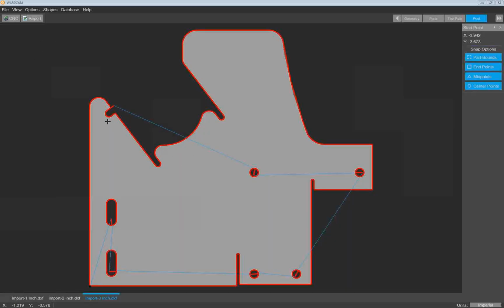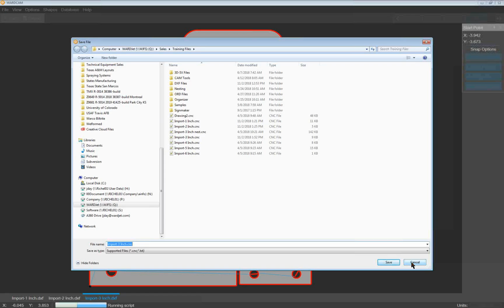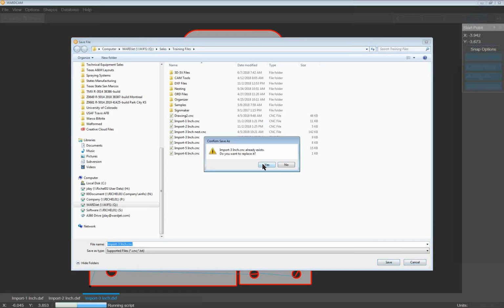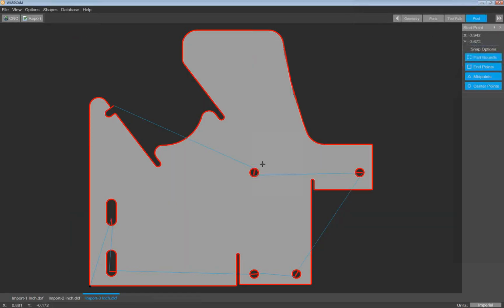Now, if you don't care about seeing the CNC file every time, or the report, if you go up to this options area on this last screen here, you've got these check boxes, and you can turn these off. So if you don't care about seeing the reports or the CNC file, just uncheck those, click on the CNC button, or the fast forward button, and it'll go through and make the files accordingly, but won't actually display them to you.